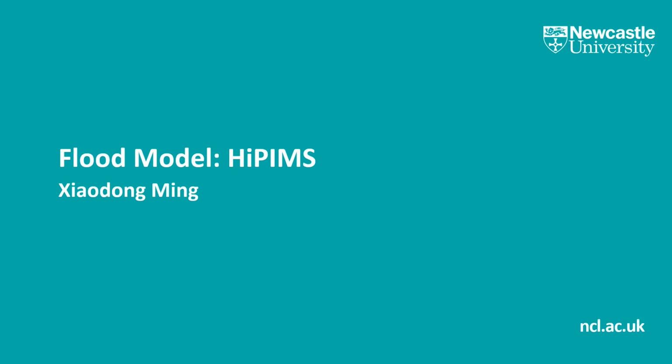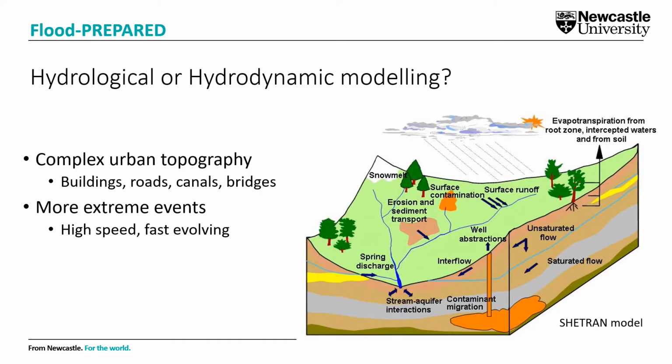In this video, I'm going to introduce HiPIMS flood model, which is applied in the flood prepared project for flood simulation and forecasting. In general, there are two typical types of flood models: hydrological model and the hydrodynamic model. Hydrological model is usually for coarse resolution, broad scale, and long-term flood simulation. It only simulates the simplified physical process of flooding and requires a lot of empirical parameters which are estimated based